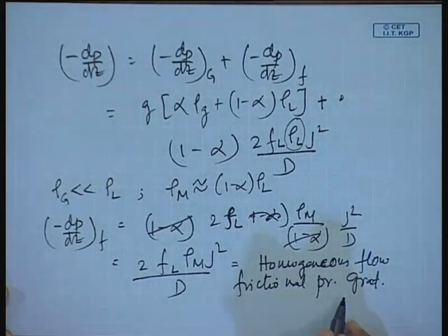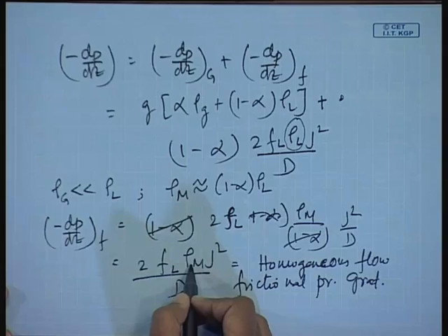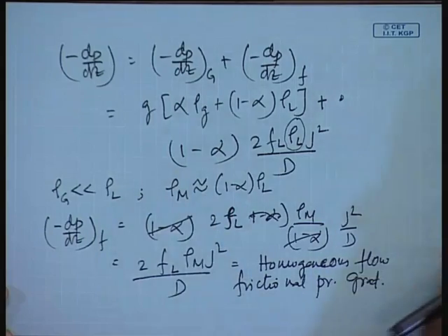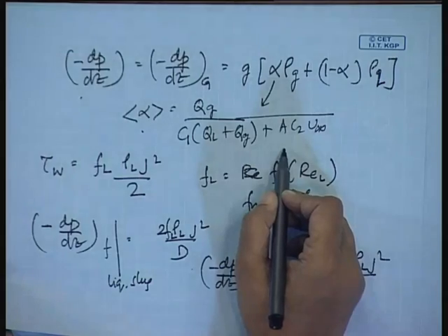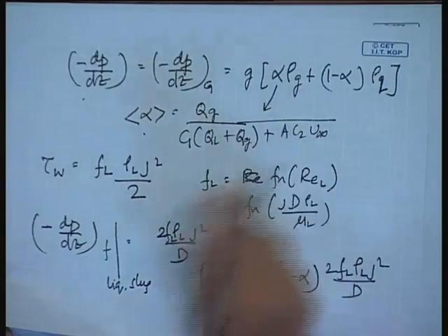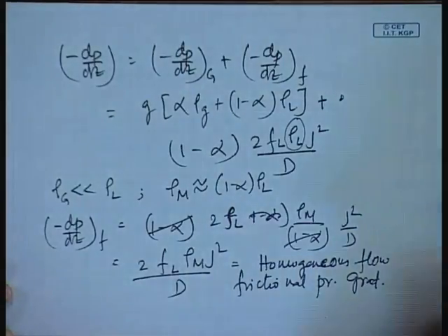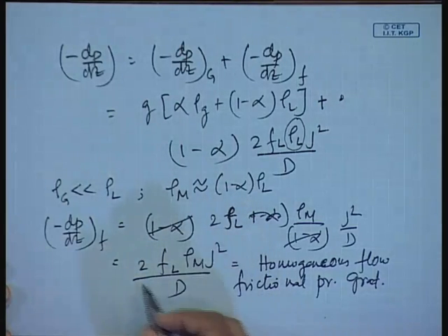where you have to remember one thing: how is it different from the homogeneous flow value that we get? The alpha which we use to calculate rho_m has to be calculated from this particular equation. This will give us a value which is different from the homogeneous flow value which we obtain under these flow conditions. Is it clear to you?